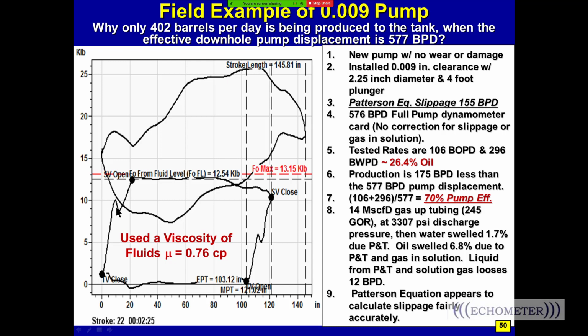What I mean by that is it takes a certain amount of time for the force to travel through the rod string, and so when you start to pick up the pump load, there is this much time from here to here. This isn't time, but there is time, and we'll look at that in a minute. As an example, it takes this much time for the wave to travel up and down the rod string, and so what we first thought when we first saw this, we thought this was an unanchored tubing, and it's not. This is not an unanchored tubing.